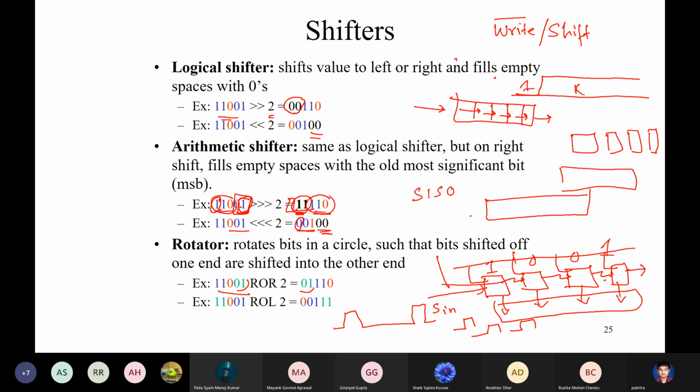Okay, so what would be the structure of the write shift signal for serial in, parallel out? Serial in, parallel out. It would be the other way around. You have to keep the shift on for k cycles till you get all the serial in, then have the write bar for one cycle when you do the parallel out. It would be the complement.